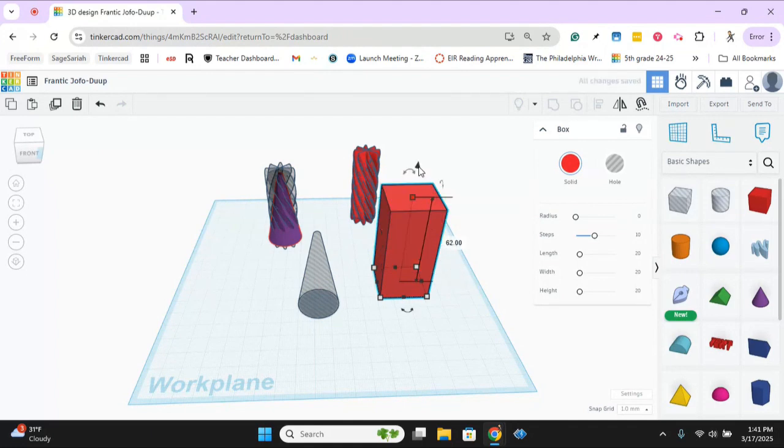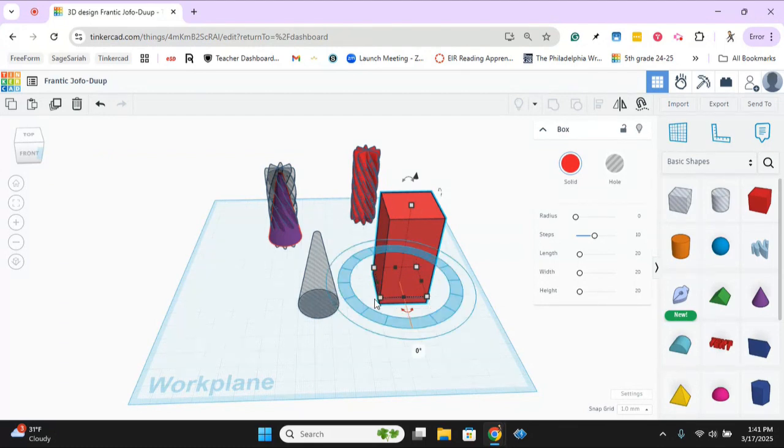And I'm also going to drop it down 4.99 millimeters. Now, the reason I'm doing that, you drop it down, is to make sure, oops, I raised it, I need to do minus 4.99. The reason you do that is to make sure the hole cuts into that whole entire shape over there, that it gets the bottom as well, just like our hole was long, to make sure that it passes through everything.